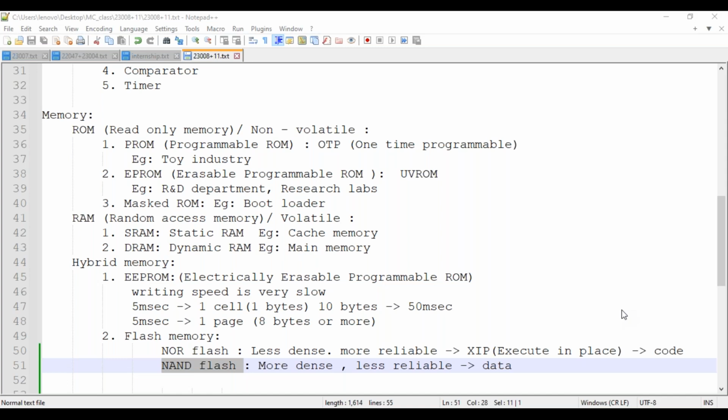In mobile, which is the ROM? It depends on the configuration of your mobile. You cannot identify which is the ROM and which is the RAM. As I'm saying, it is generally the flashes which are being used. But there will be a mask ROM available in all of your devices which will have the bootloader written.